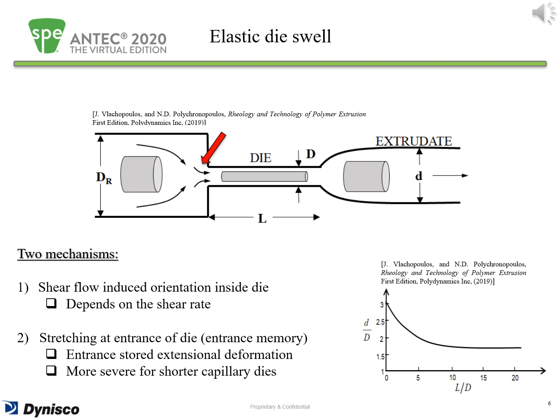Moreover, other kinds of undesired flow instability and extruded distortion, such as elastic die swell at the exit of a die, can happen during the capillary extrusion process due to the elastic nature of polymeric fluids. For the origin of the die swell of viscoelastic polymers, there have been various interpretations such as normal stress effect, elastic energy effect, orientation effect, or memory effect.